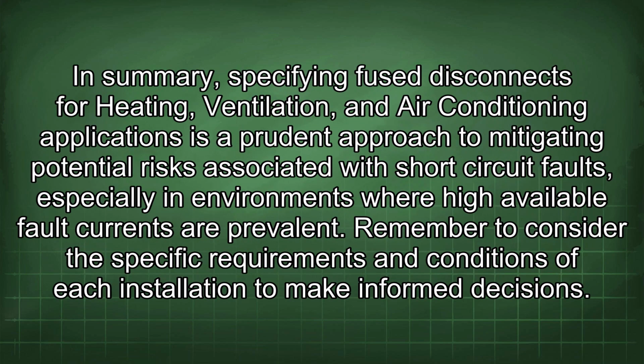In summary, specifying fuse disconnects for heating, ventilation, and air conditioning applications is a prudent approach to mitigating potential risks associated with short-circuit faults, especially in environments where high available fault currents are prevalent. Remember to consider the specific requirements and conditions of each installation to make informed decisions.